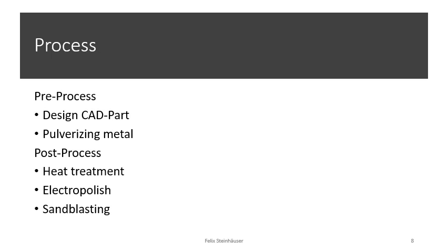Then you can have a heat treatment to release tension in the part or harden it, but the part is already very hard because it has a rapid cooling in the machine, so you mostly get a harder part than if you would mill it.